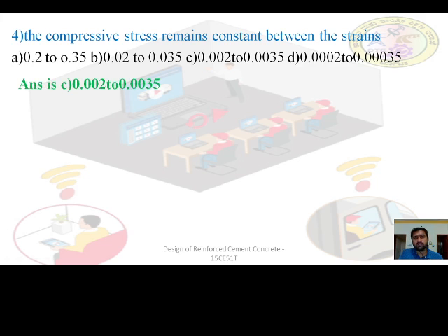Okay. So between the strain 0.002 to 0.0035, the compressive stress remains constant, the rectangular part. Just to confuse on the decimal numbers, I have given this question.